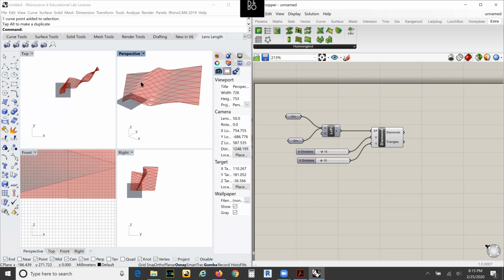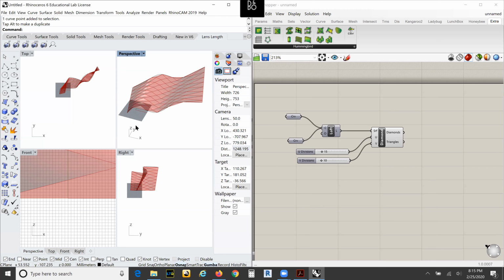Well, Hummingbird allows us to convert Rhino geometry into an Excel spreadsheet, and then Revit will read the Excel spreadsheet and create a native Revit family out of it. And so now our crazy Rhino forms can be in Revit and they're BIM, and it just makes a great workflow.